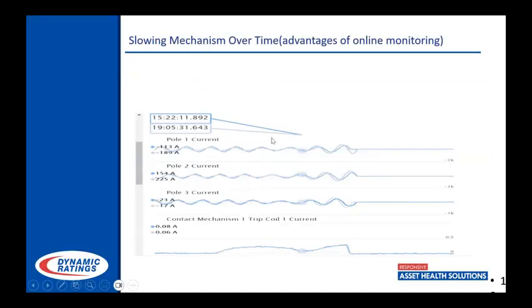So this was an actual online monitoring lubrication issue that was captured. Just to give you a brief history on this, when this monitor had been in service around 8 or 9 months, this was what the typical waveform overlay looked like. So we can see our low current, we can see no latch apparent on this one, but we do see that this buffer is being struck at roughly the same point. And we also see this 52A is rolling off within 1 millisecond of every time this breaker operated. And so going through the data, this went on for 8 or 9 months.